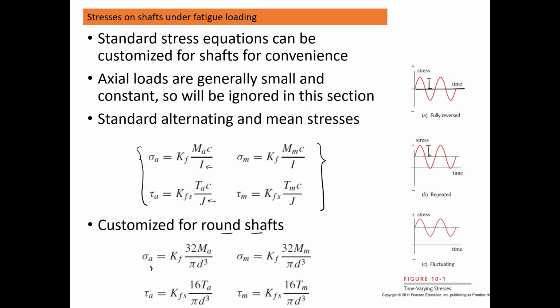If it's fully reversed, which means you have a shaft under a load, let's split this shaft above and below the center line. So we have A, for example, here. So in the first instant when you start, it would be under compression. If I'm only looking into A, this portion below, it's under tension. After 180 degrees rotation, it's still the same, so that's A here. So after 180 degrees,